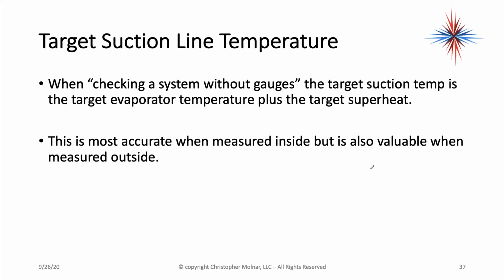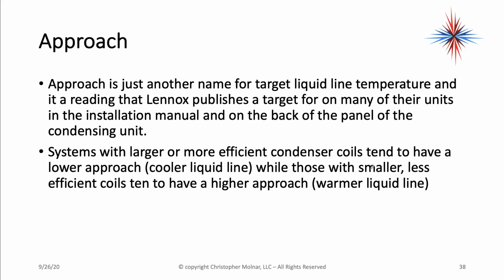Target suction line temperature, again, the target suction temp is the target evaporator temperature plus the target superheat. It's most accurate when measured inside, but it's also valuable when measured outside. It's going to be a couple degrees difference.